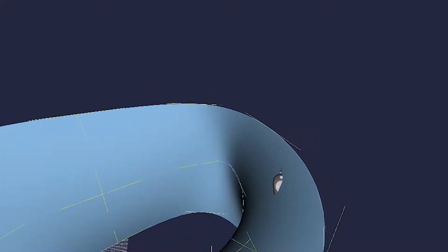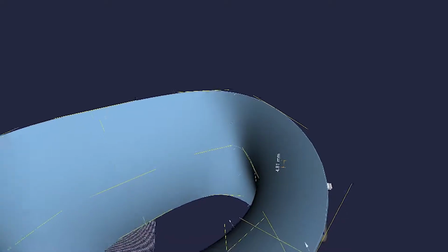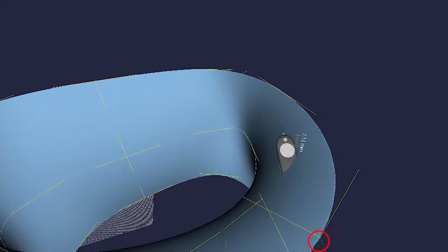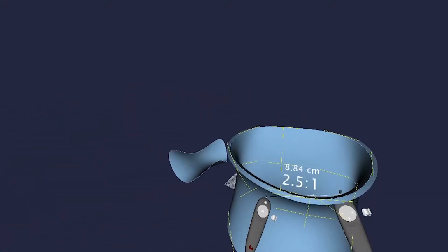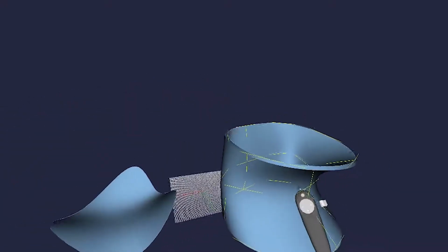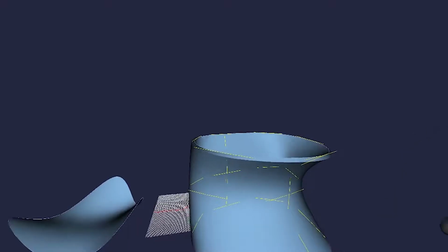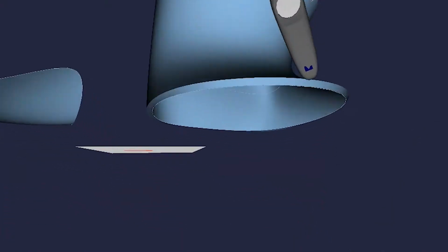And then next I'm going to zoom in and perform the offset command, which basically gives thickness and volume to that lofted surface. Notice the little arrow at the bottom right showing you the direction and the amount of which it's offsetting. Now I'll go ahead and deselect, and then just kind of look around the model, from underneath and above.